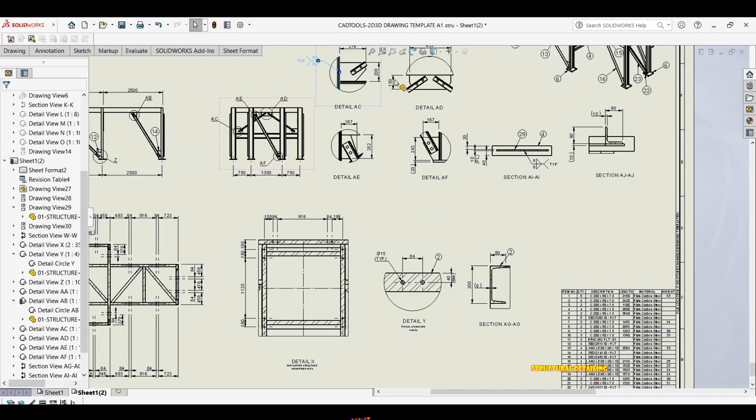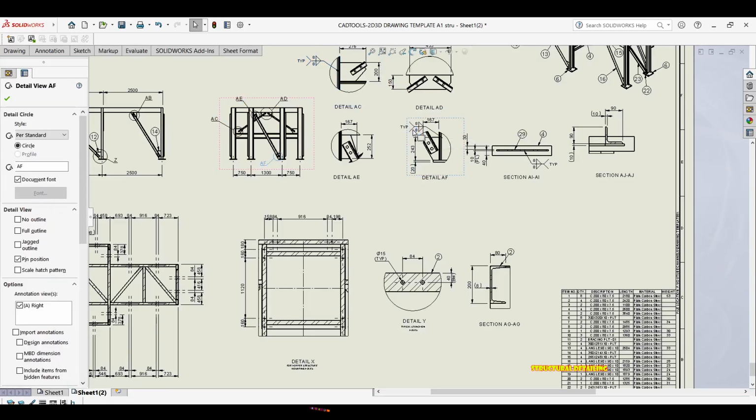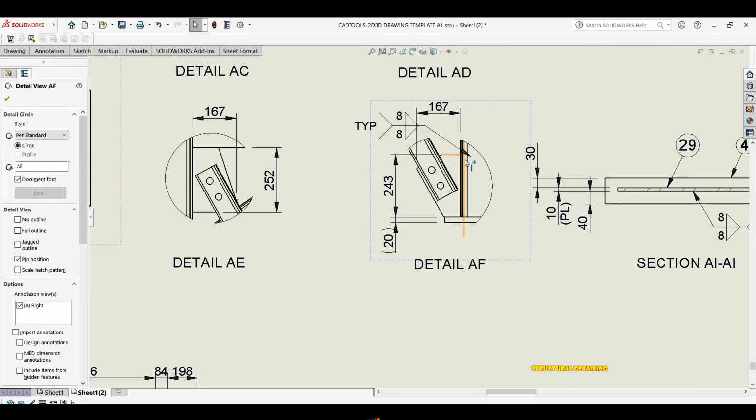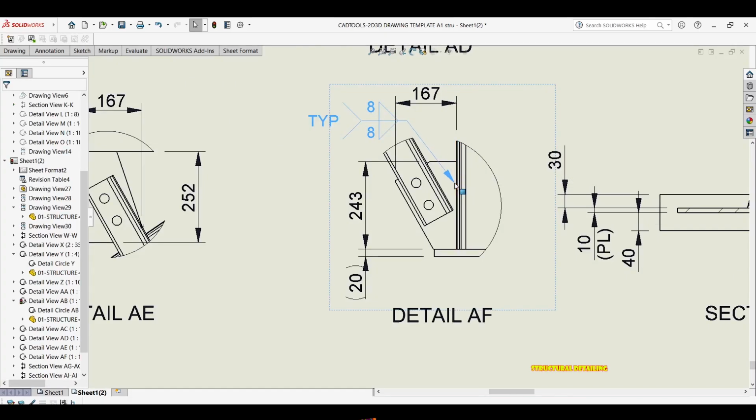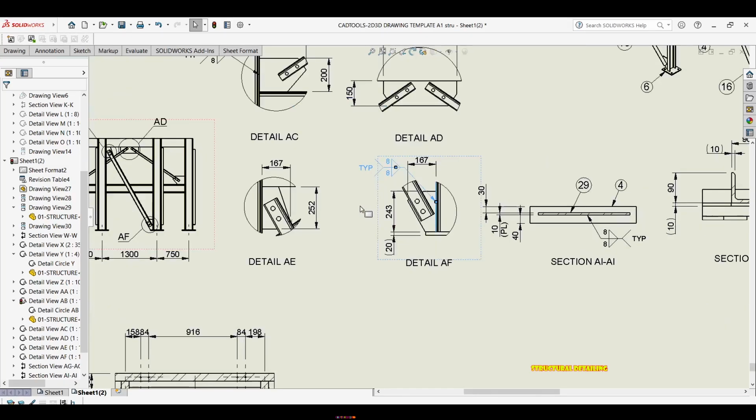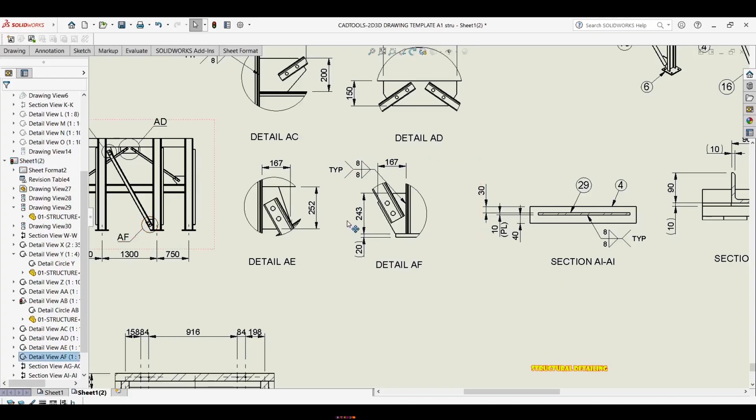I was saying you can copy a weld symbol. So look, copy, paste. You copy and then you paste it, but you have to click inside the viewport. You know why you click inside the viewport to paste? I'll show you why. So that if this view moves, the whole thing moves with it. The symbol moves with it.